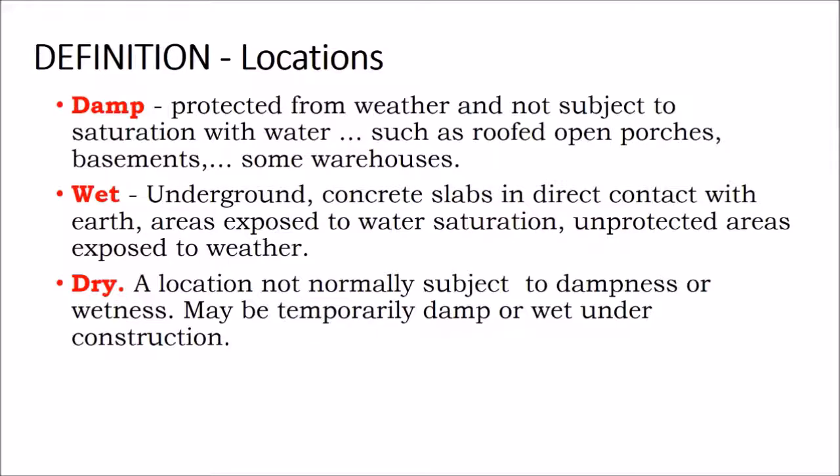Same with solar modules. Your solar panels are designed to go up on the rooftop for a long period of time as well. The danger is during construction, if the array is not fully complete, you might have loose connectors and wiring hanging off all of these components. And I have seen damaged electronics where the install crew might mount the optimizers or microinverters at the end of the day, and then they don't plug them up and it rains overnight. Water gets into the connector.